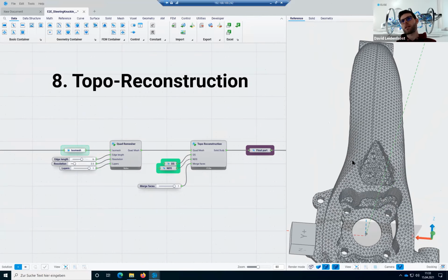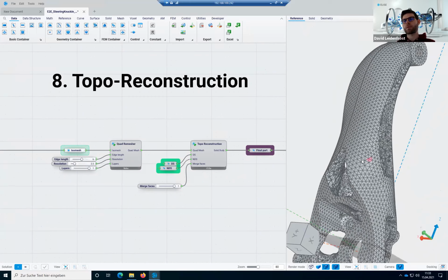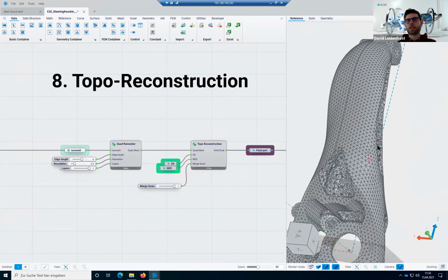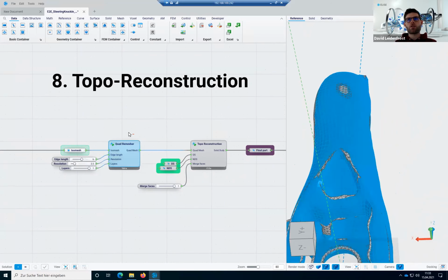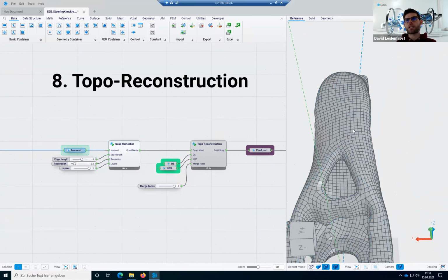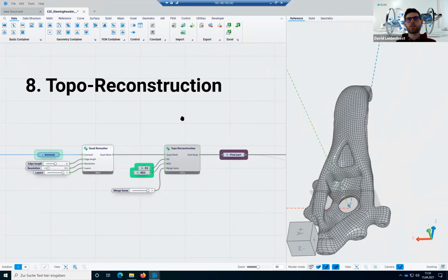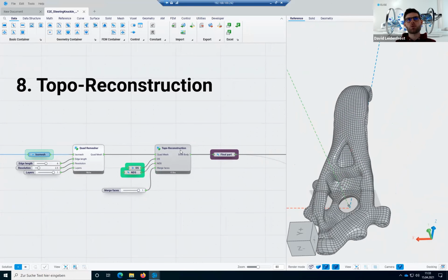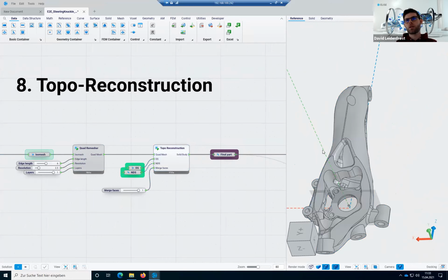The ISOMesh consists of many, many little triangles, and is most of the time not a very nice mesh, has many self-intersections and so on. And with the quad mesher, we can generate out of this ISOMesh a really nice quad mesh. And once we have done this, we can use the sub-D algorithm to create a solid part out of this quad mesh.